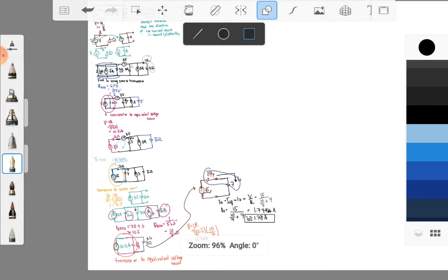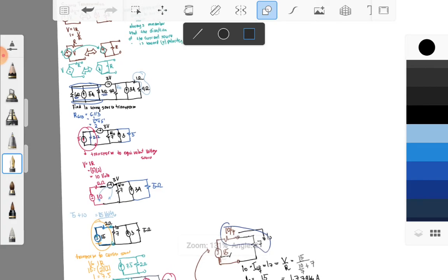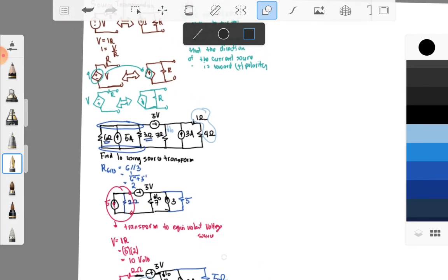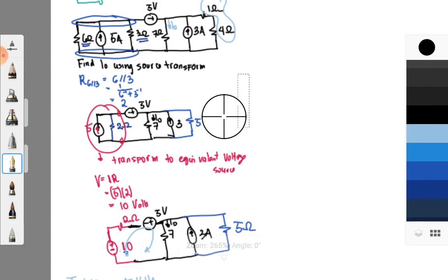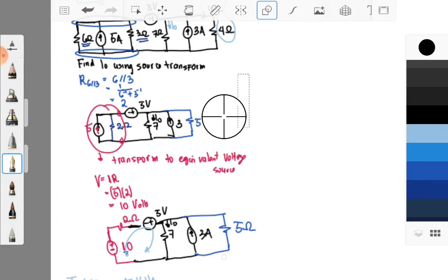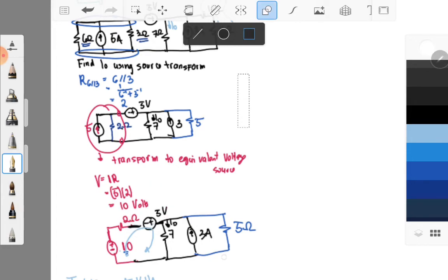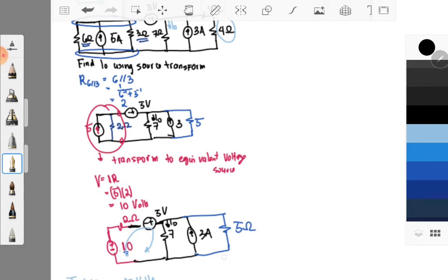So did you recap the topic? You will notice that the first thing I did was to solve the 3 and 6 ohm. After that I recognized my voltage source transformation into my current source transformation. Then in order to check whether these two voltages are additive, I made a loop or KVL at loop 1. So upon KVL at loop 1, I noticed that the two voltages will add up. So therefore I will add them as a positive I1.